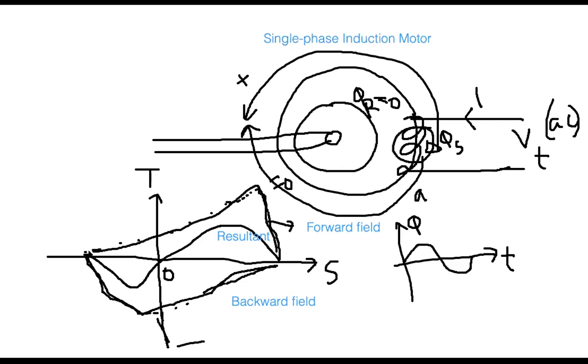If you remember the induction motor characteristics curve, torque versus speed, in the three-phase system, this point is called the pull-out torque or the maximum torque. So one curve is going in that way and the other curve is at the bottom, in the reverse direction. Then I connect them point to point. I just drew it by hand, it does not look equal, but it will be equal. Meaning that the resultant curve at the zero point has a torque value of zero. That is the meaning that its starting torque is zero at zero time.